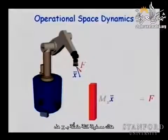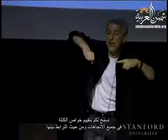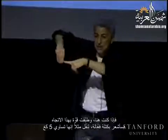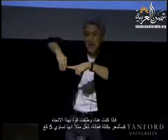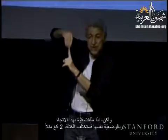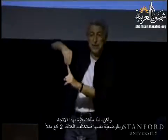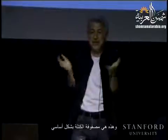There is a mass matrix associated with this X that allows you to evaluate the mass properties in the different directions and the coupling between them. So if I'm here, and if I push in this direction, I will feel sort of an effective mass of, say, 5 kilograms. But at the same configuration, if I push in this direction, the mass is different, 2 kilograms. And if I rotate about this axis, I will feel some inertial force that is different from this one. And this is your mass matrix, basically.